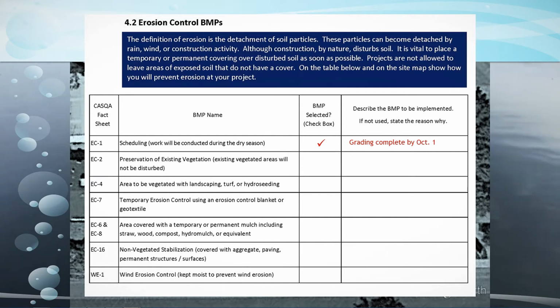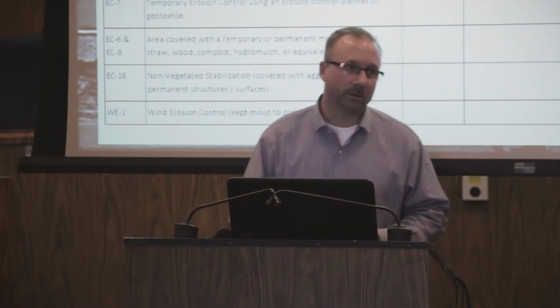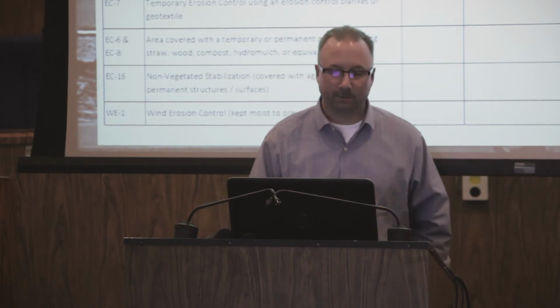All right, first one, EC1, scheduling. And in this case, for this project, we said yes, they're going to get the grading done before the bulk of the rainy season comes in. And so they're going to use scheduling to their benefit to get a lot of that soil disturbing work done early in the season before we get the rains.